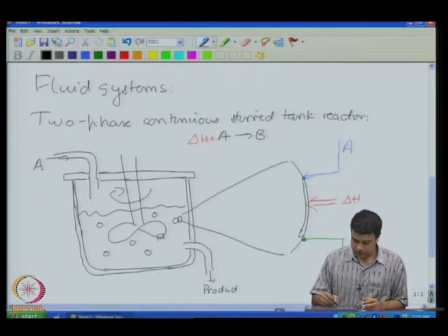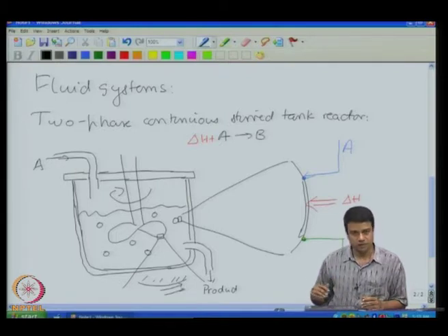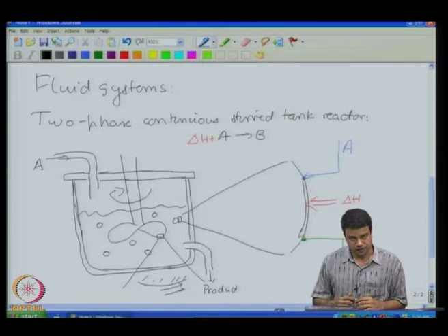So, if I look closely at the interface between the impeller and the fluid, there is the impeller surface and there is fluid that is flowing past the surface. At the surface itself, the fluid has to have the same speed as the impeller, and then there is a variation of the velocity of the fluid away from the surface. Now, this fluid motion generates fluid friction, and that exerts a backward force on the impeller. In order to compensate for that, you have to exert a power on the impeller.